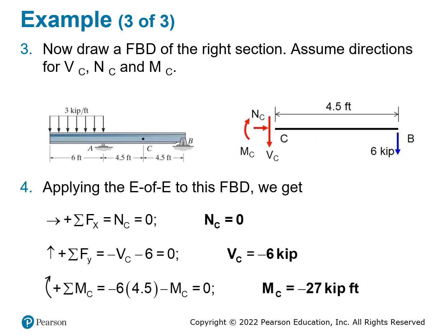So what do you do after you find that? Well, our purpose is to find out what is the internal force at this point C. So we have to cut at C to find the solution. When you cut here, we have two parts: the part on the left and the part on the right. In this example, we use the part on the right, which is this one here.